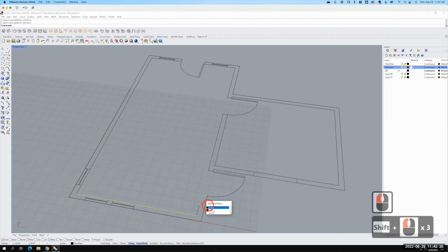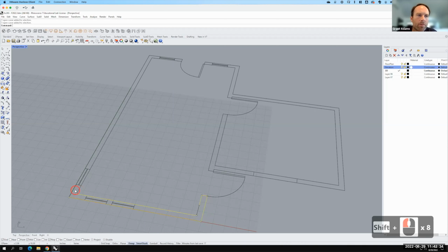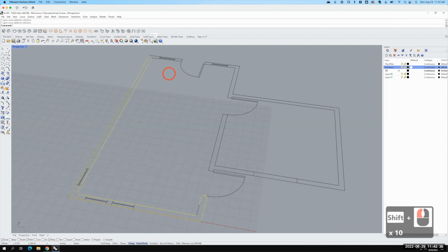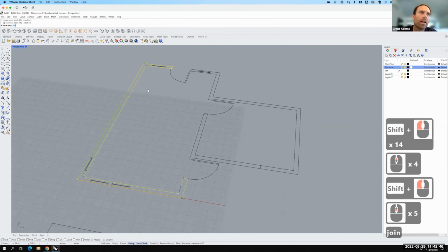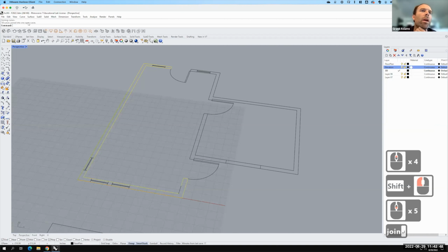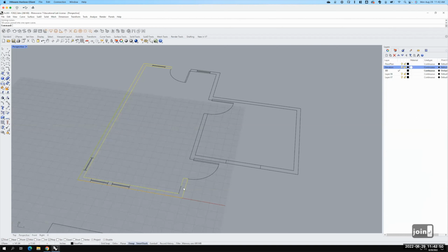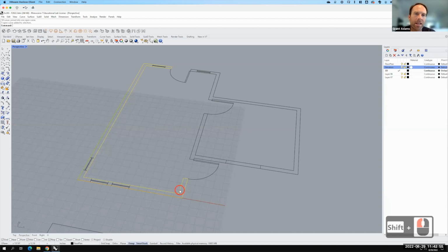as you select them, you may get a result like this. And when we type join, 10 curves joined into one open curve. Well, the reason that that's an open curve is because it doesn't connect all the way. Even if I came back and selected this curve and then joined again, it looks closed, but you see that it's still showing that it's joined into one open curve.